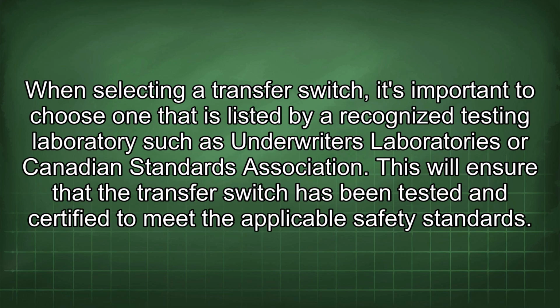When selecting a transfer switch, it's important to choose one that is listed by a recognized testing laboratory such as Underwriters Laboratories or Canadian Standards Association. This will ensure that the transfer switch has been tested and certified to meet the applicable safety standards.